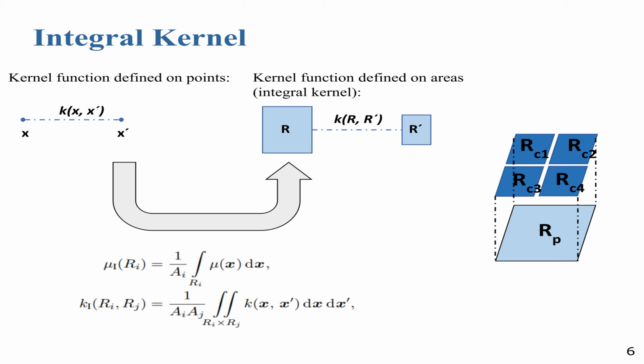In our mapping approach, we initialize our map to the highest resolution and monotonically reduce the total number of grid cells by merging operation, which facilitates online mapping efficiency, while maintaining spatial correlations of the map in a theoretically sound fashion.